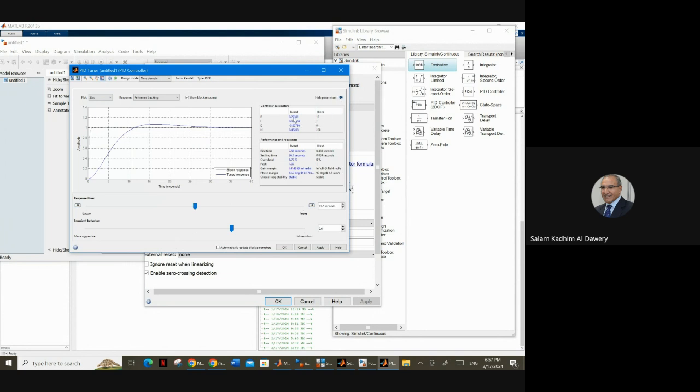It says Kc equals 0.29. They reduced Kc. And here is the value of I. In our block, what we had before was 10 and 1. Here it is 0.2 and 0.04, but the inverse of 0.04 or 0.05 should be almost about 50. That's why it takes a longer time to reach the steady state, within 35 seconds. It depends on your time constant. You may say I need this one, but the application will not be easy in a control system. The controller will start rippling.